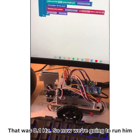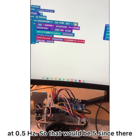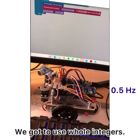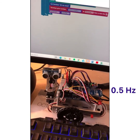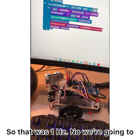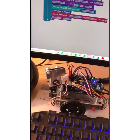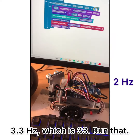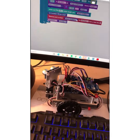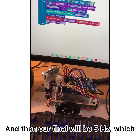That was 0.1 hertz. So now we're going to run him at 0.5 hertz. So that would be 5. Since there are no decimals in Blockly prop, we have to use whole integers. So that was 1 hertz. Now we're going to do 2 hertz, which is 20. Run that. 3.3 hertz, which is 33. Run that. And then our final will be 5 hertz, which will be 50.